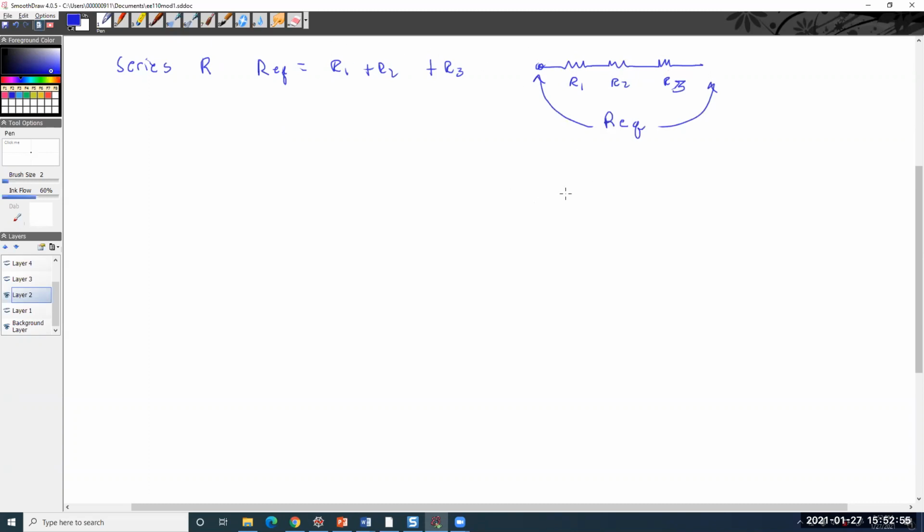Well, if I do this for an RLC circuit, Z equivalent is ZR plus ZC plus ZL, which would equal R plus 1 over SC plus SL. And you have to know the frequency in order to actually get a number for it.